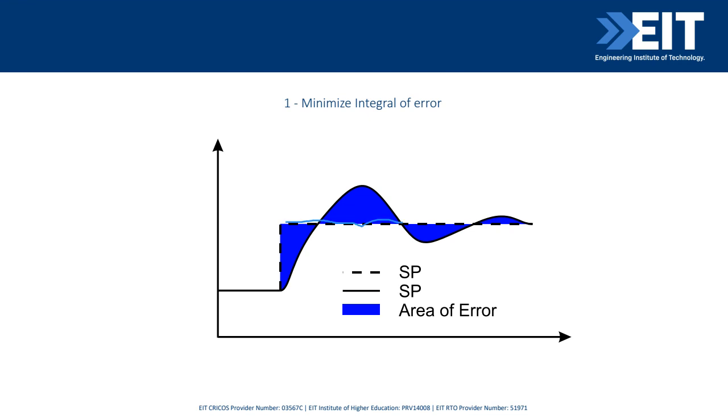So we're targeting that particular value. Then the other value, which is also really important, is obviously the process variable, this thing here, which will go up and going down. That's the process variable, PV. So we're going to abbreviate it PV, and I'll show you a loop controller in a minute. But the process variable. So obviously the whole idea is that your process variable settles down spot on with your set point.